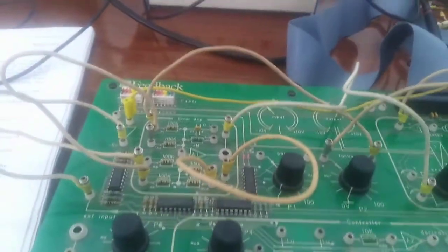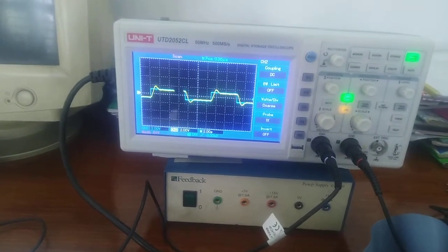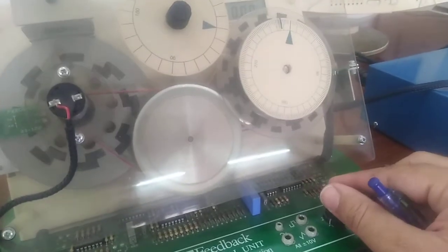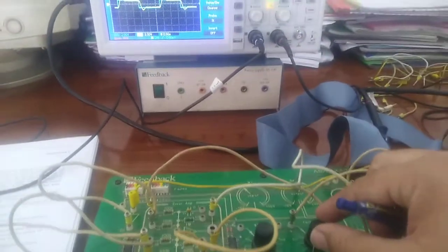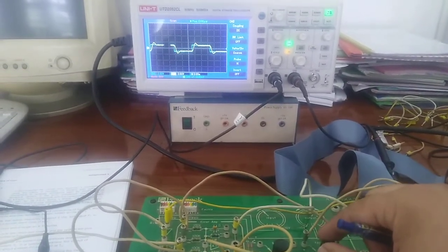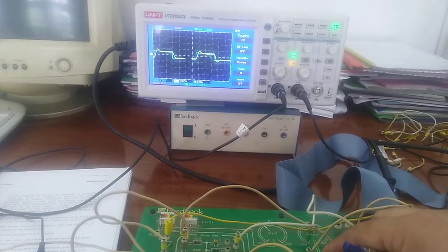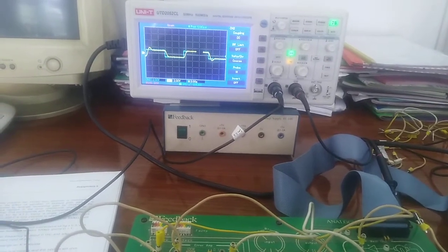So in this case, you can see here, this is the response. The yellow is the response of the DC motor, and it can be seen here on the motor. We can similarly change the frequency of the machine as well. So now I am applying the velocity feedback with this potentiometer here, so you can see, and the response of the motor will be very smooth. So you can see here the difference. Now the DC motor is following exactly the square wave input.